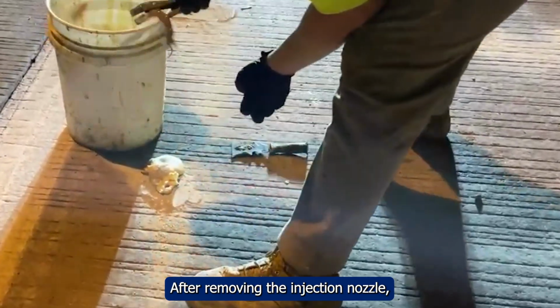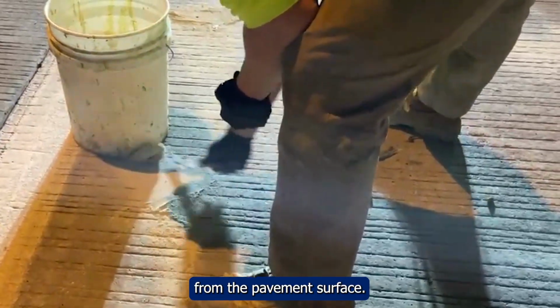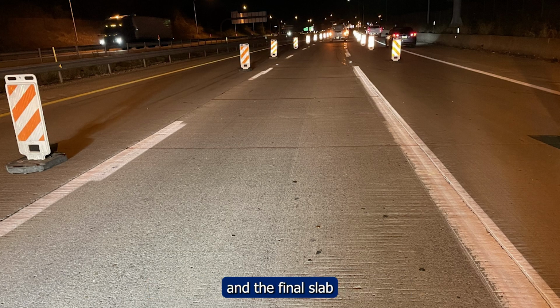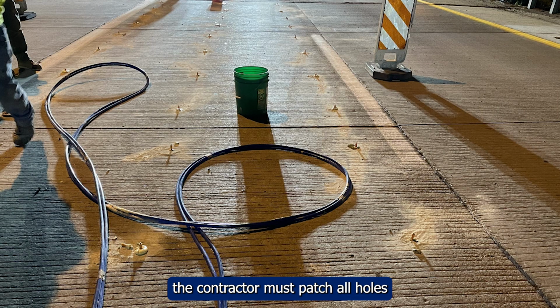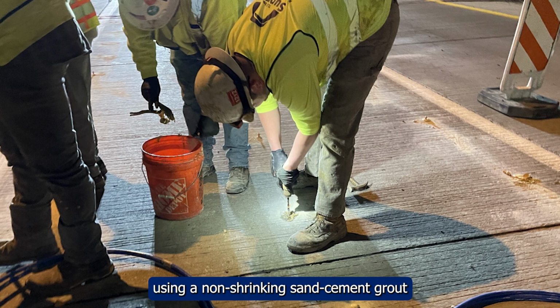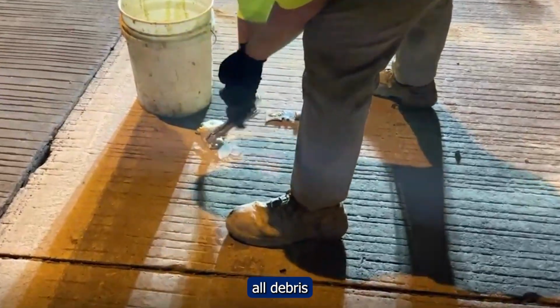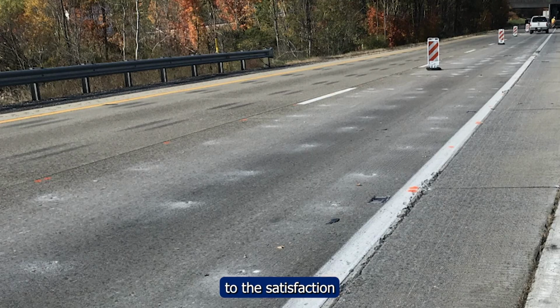After removing the injection nozzle, the contractor must remove any excess material from the pavement surface. Pumping must cease immediately upon any sign of vertical slab movement, and the final slab alignment must be confirmed to ensure proper drainage. After injection has been completed, the contractor must patch all holes using a non-shrinking sand, cement grout, or an approved quick-set patching material. At the end of each workday, all debris resulting from slab stabilization operations must be thoroughly cleaned up to the satisfaction of the department representative.